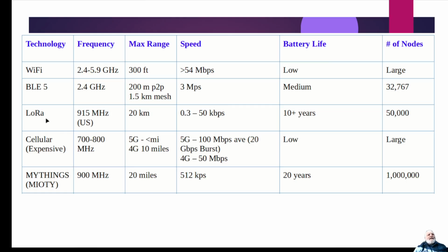On the other hand, if we use some of these low power ones like LoRa, it's very low data, but it's also very low power. So if you just have a remote sensor sending temperature data or pressure, weather data, and you just have it mounted far away, all you're doing is just sending these few updates every minute or every few seconds.